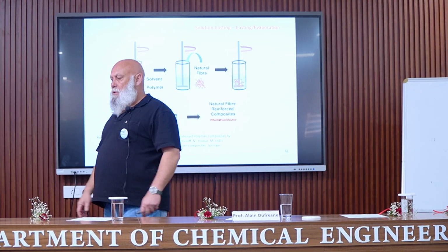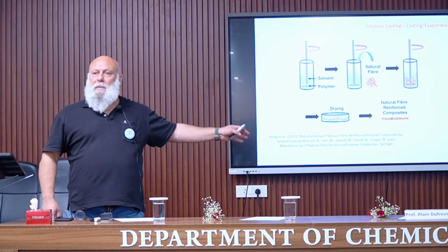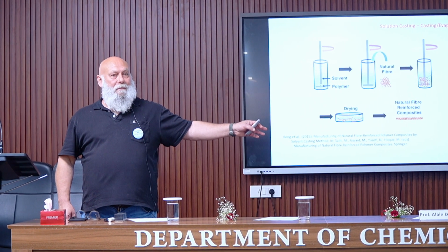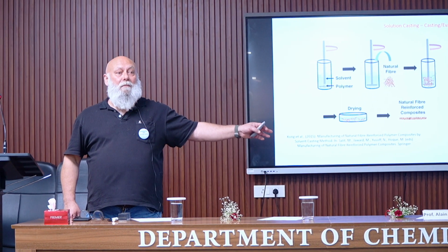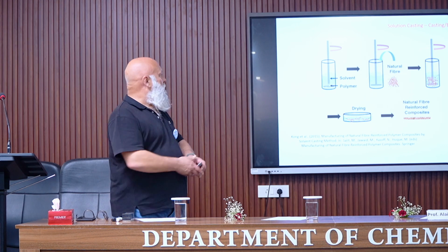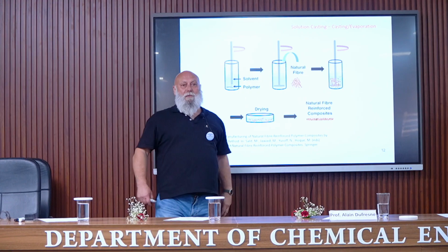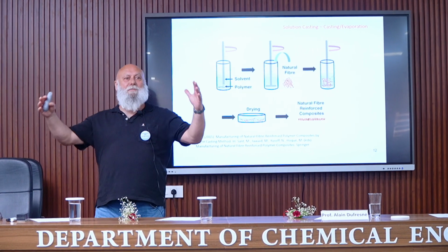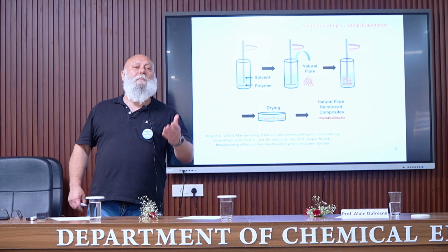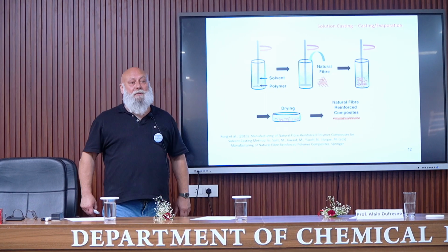What is the main drawback of this processing technique? Homogeneity can be a problem, but imagine that the polymer is well dissolved and the fibers are well dispersed in the liquid. Homogeneity is not a problem in this case. Now, the main problem, yes, you have a high amount of liquid to remove, meaning that it's a long process.